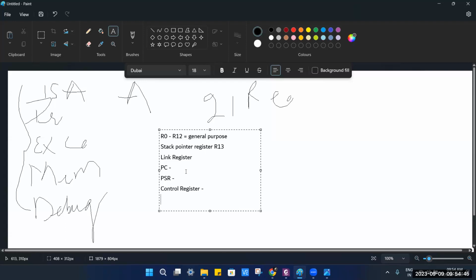After that, there are the special purpose registers. You might have heard of PRIMASK. Priority interrupts are there, specifying which one you will execute. And if a fault has occurred, there is also FAULTMASK, similar to that. A hard fault is very generic. And then the last, as per my understanding, is BASEPRI, the base priority mask. Mostly it is used as a threshold for interrupt priority.